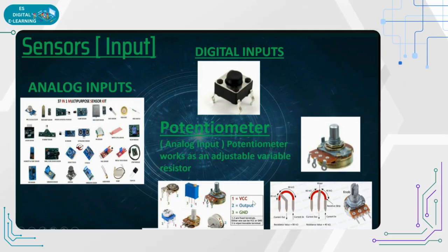It is a potentiometer, so that will be an analog input, whatever we are giving as the input. So what exactly do these sensors have? Remember, this is very important. The sensors have three pins. They have the power, ground, and output, which is nothing but the signal or the feedback signal. What are the three pins of the sensor? Power, ground, and signal, or that signal is the feedback. The signal is the output, meaning the sensor will read the input data and send it to the controller. Getting it right? That is the output. Are you able to understand it?